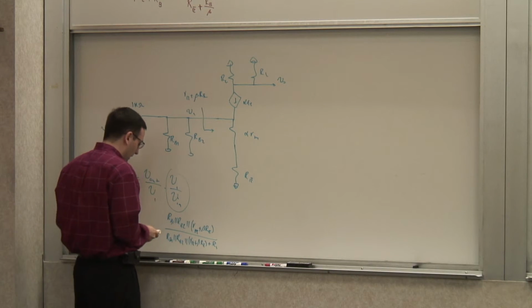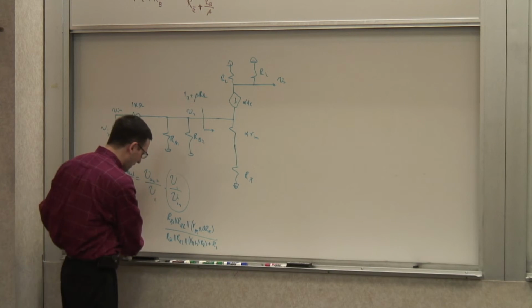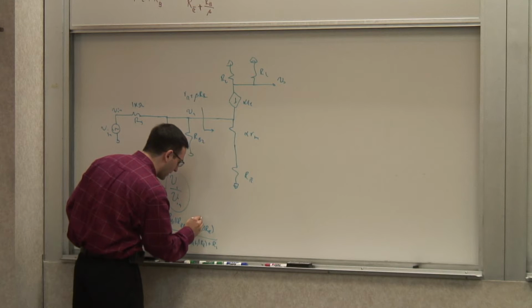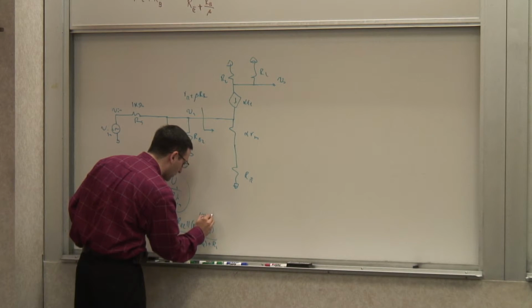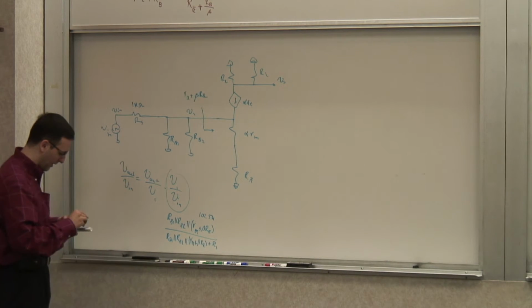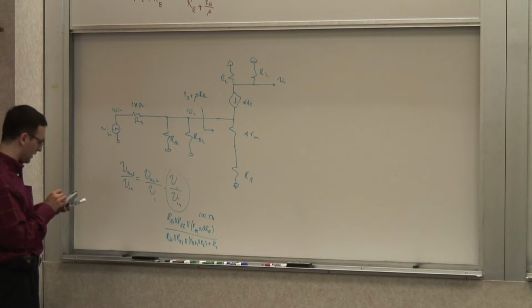Okay. Well, I have to do this parallel combination this time. So first I have to calculate this. I know this is 100 and this is 2.5K, so that's 102.5K. And RB1 and RB2, so I have to calculate the parallel combination. So let's put that 105 times, was it 83, 82?